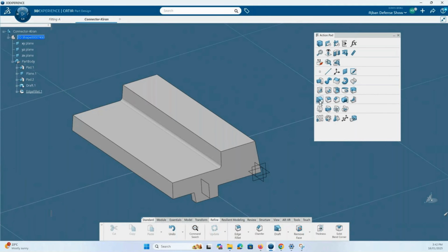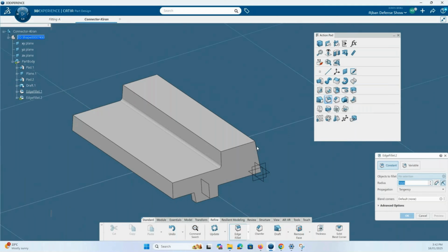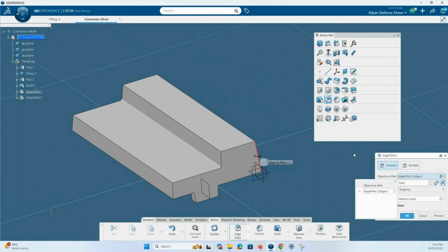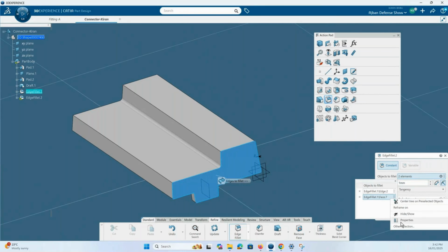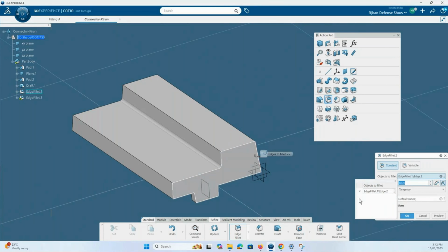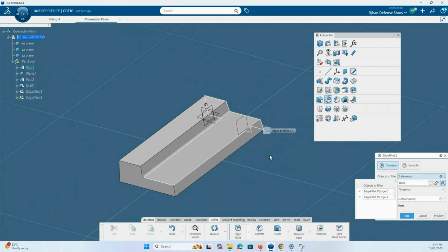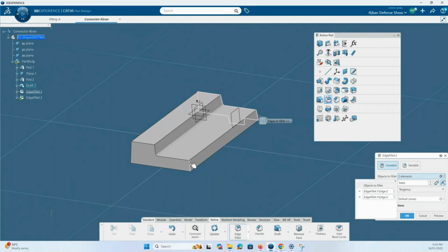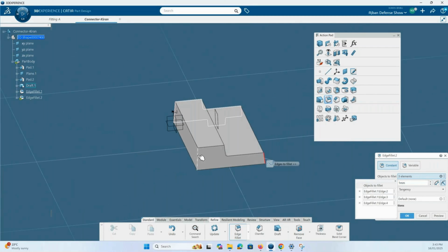Okay. So again, we can look at the edge fillets. You don't need to control select, actually. Just open this object bar here, and if you've made an incorrect selection, you can come here and delete it from here. Okay, you've got one selection in. You can look at another one there. I'm going to speed up here. I'm going to look at another one here, another one here.